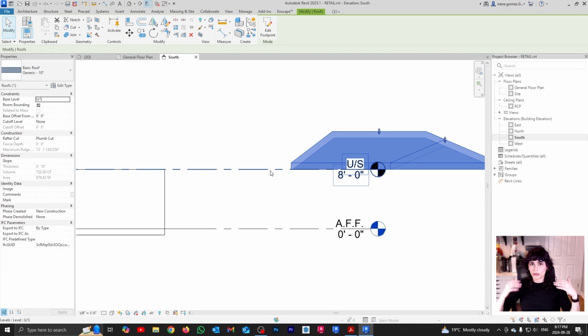When you create a roof, the roof is extruded up from the level. So the reason that we use roofs, even if I know that realistically what should go here above is a floor, is because in modeling sense, this will make things easier for you. Because then you don't have to be calculating, oh, like my height from floor to ceiling, plus the thickness of my slab, plus this, plus this, plus that.